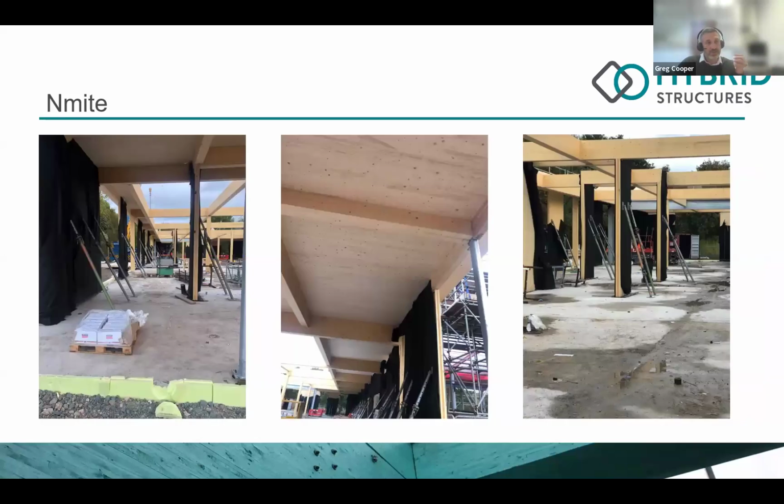So some images there. You can see heavy props in here to erect it. We haven't gone OTT on the temporary works. We don't need that many props. That's more because of the thrust load from the roof during the construction phase. So as it's being built, we put the props in, it's safe, it isn't going to spread, and it's going to tie itself all together.